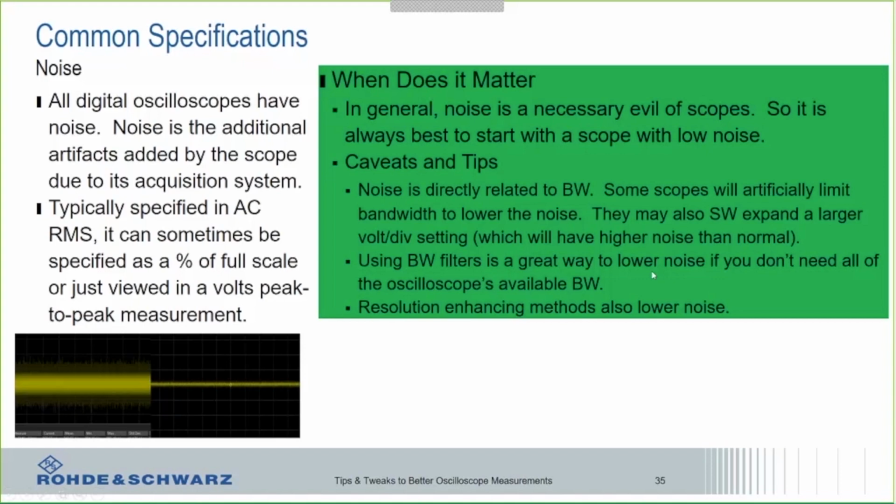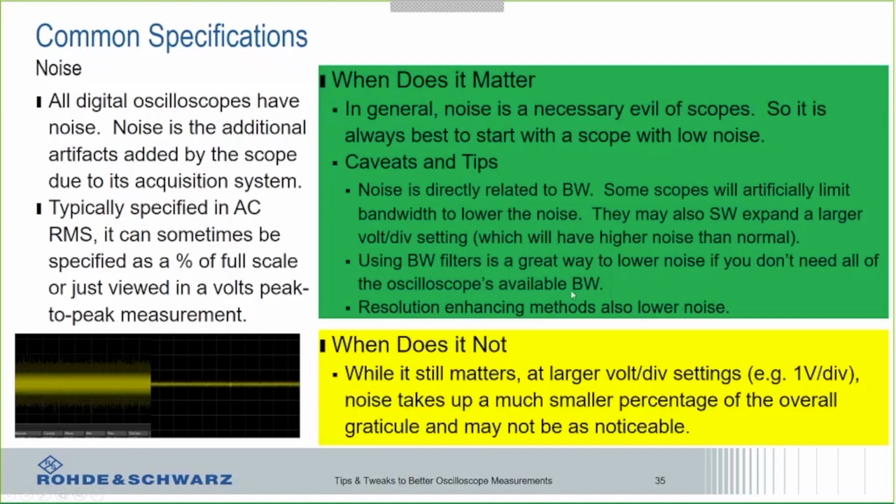Using bandwidth filters, as I mentioned, is a great way to lower noise if you don't need all the oscilloscope's bandwidth. So knowing how much bandwidth you need can really come into play here. Those resolution enhancing methods that we talked about are also important.